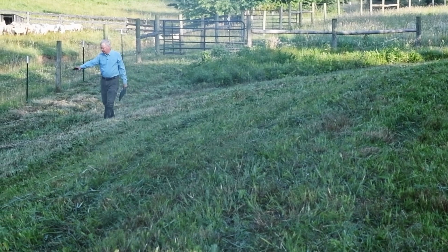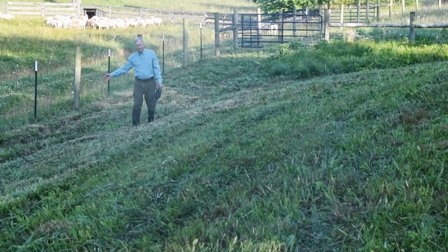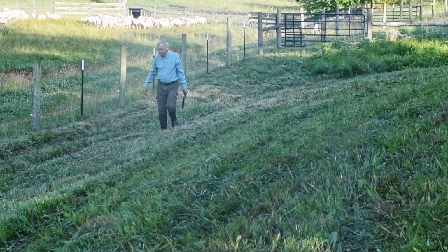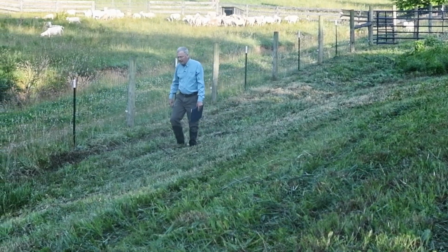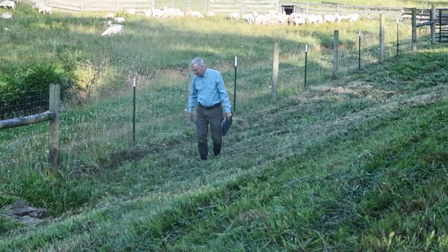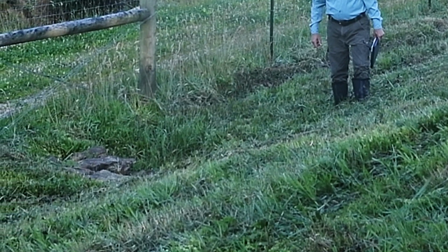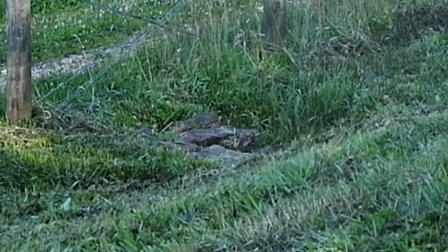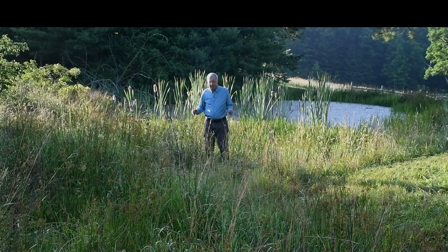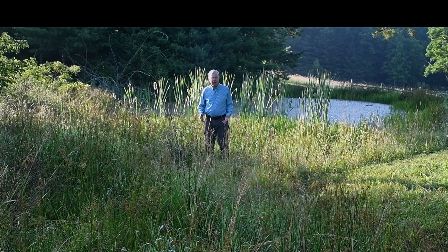Here's some ruts along the lower edge of the dam. That's where water's been collecting next to the neighbor's road. Now I'm coming up on the outlet for the drain pipe. I have it rocked so there's no erosion. There is water flowing in it. No seeping. Here's the entrance to the spillway that carries water around the dam without causing erosion.